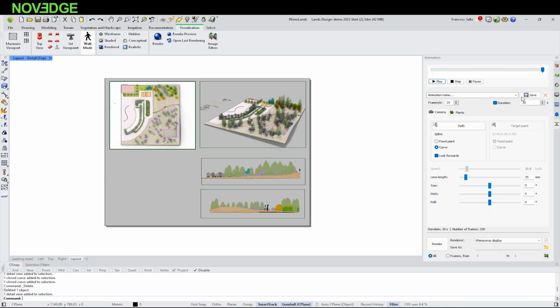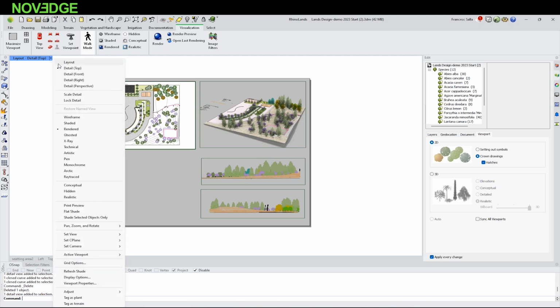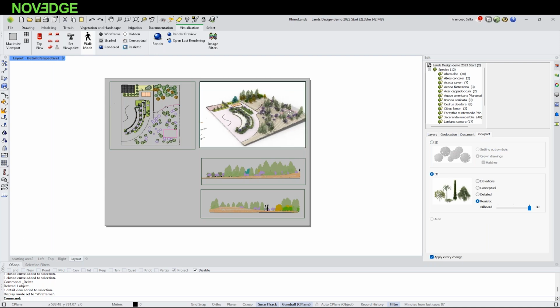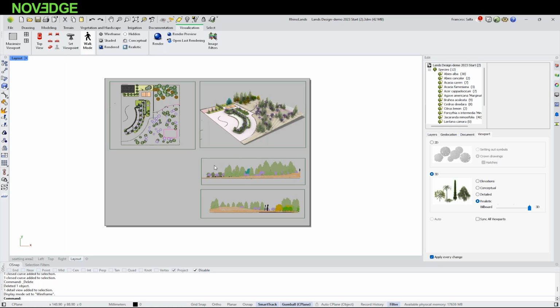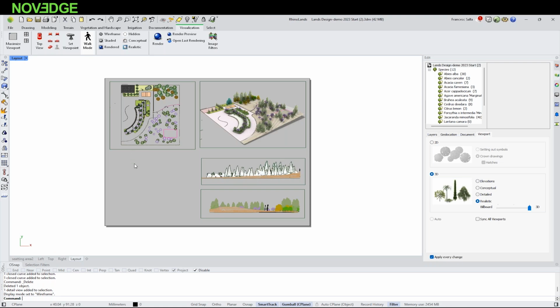So we can have one detail for the top viewport. Here I can go to the edit panel and show this view in 2D. Maybe I'm going to show the wireframe inside this view, while in this other detail I'm showing the 3D view. Maybe in this detail I can also show an elevation or a section of that view, or I can select the elevations. And maybe we can insert another detail to see maybe all the list.